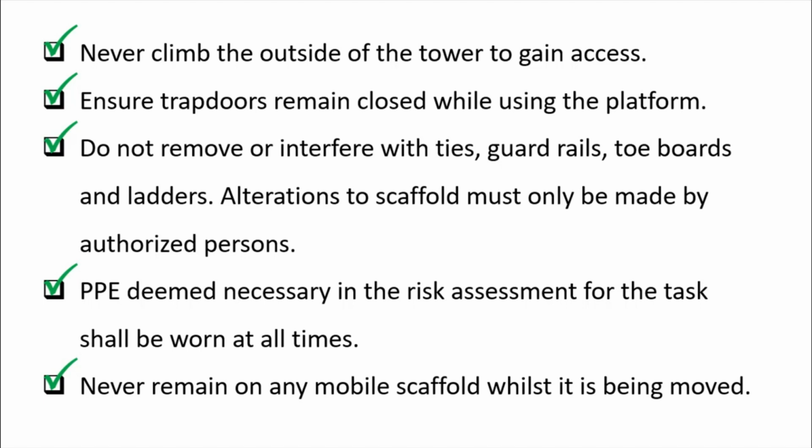So before you move or transfer the mobile scaffold from one place to another place, all persons should go down to the floor before transferring of that mobile scaffold, because when you are moving it may collapse because of unbalanced movement of the personnel on the top, and the center of gravity of the scaffold may be compromised, and then it will tip over and it will be a disaster if someone gets injured or dies.